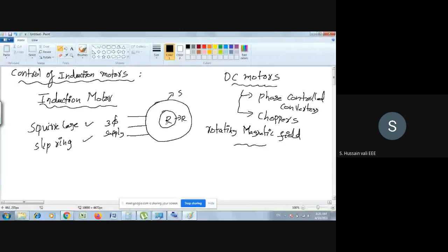So now the stator magnetic field and the rotor magnetic field both will interact. When both interact, as per Faraday's law, or using the basic principles we have, a torque will be produced. As one cylinder is the stator and the other one is the rotor, the stator is rigidly fixed. Only one option is there, that is the rotor, so the rotor tends to move in a particular direction.